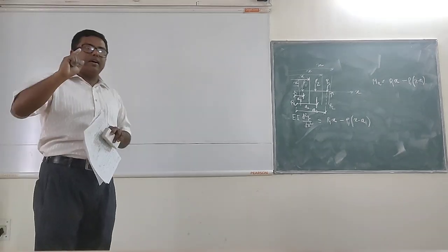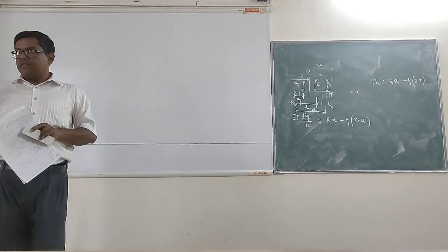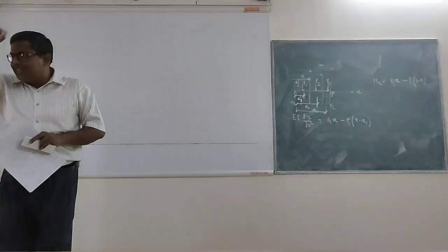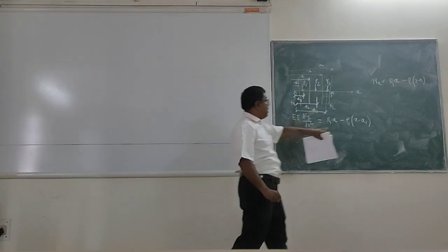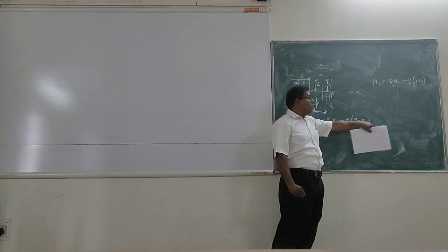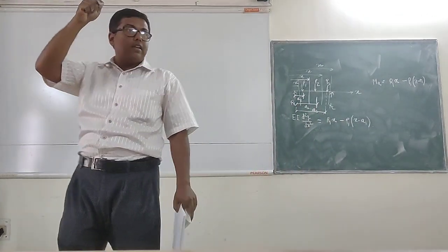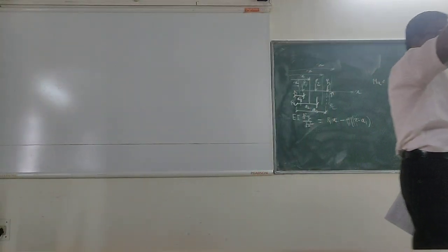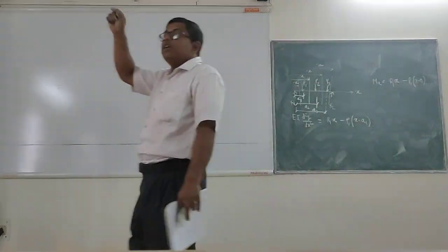This way, Macaulay proposed a generic equation for the double integration. Depending on the value of the boundary condition, if the terms inside the brackets become equal to 0 or negative after putting the values, I should not consider them for the equation.